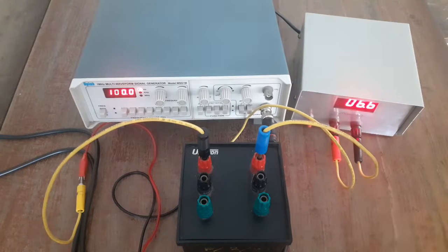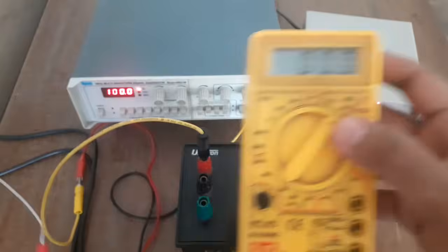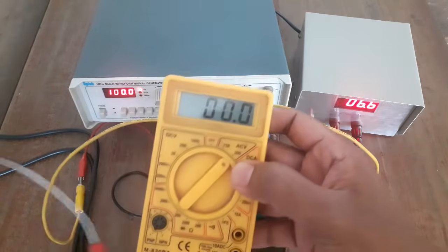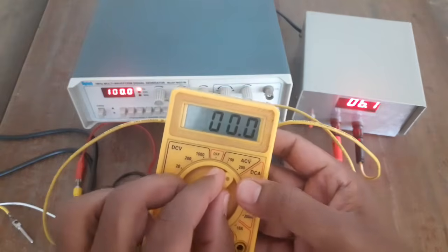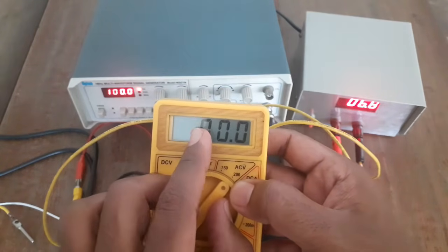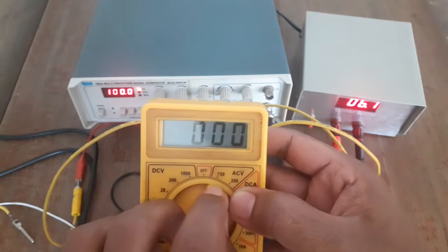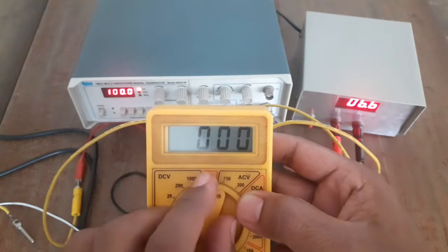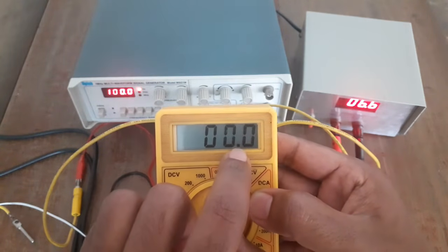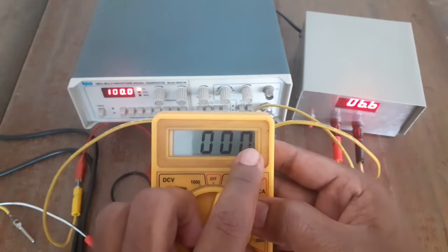For that I am going to use this digital multimeter set at AC volt measurement. There are two ranges, 750 and 200. The meaning of it is, if I have it at 200, it is going to measure AC voltages up to 200 volts. If I have it here, it is going to measure AC voltages up to 750 volts. But you see that at 200 you are going to have one extra decimal point of accuracy, right? See, there is a point something. For 750 you don't find it.